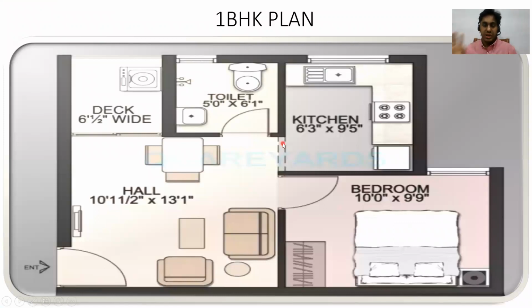Okay, let us say you have a plan of a 1 BHK. I'm taking a random example here. If you come to me for a 1 BHK plan, this is how a plan that I'm going to give you looks, right? You're making an entry to your home from here. You have a small hall here. I'll be giving a toilet here, which is 5 feet by 6 feet 1 inch. Then I'm going to give a bedroom here, which is 10 feet by 9 feet 9 inch. Then you have a kitchen here. So it's a small 1 BHK plan. You can see here one bedroom, one kitchen, and a hall is given here, right?